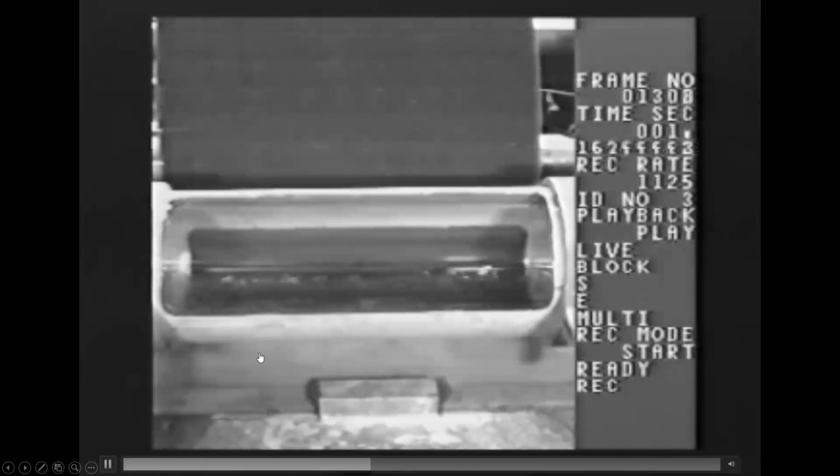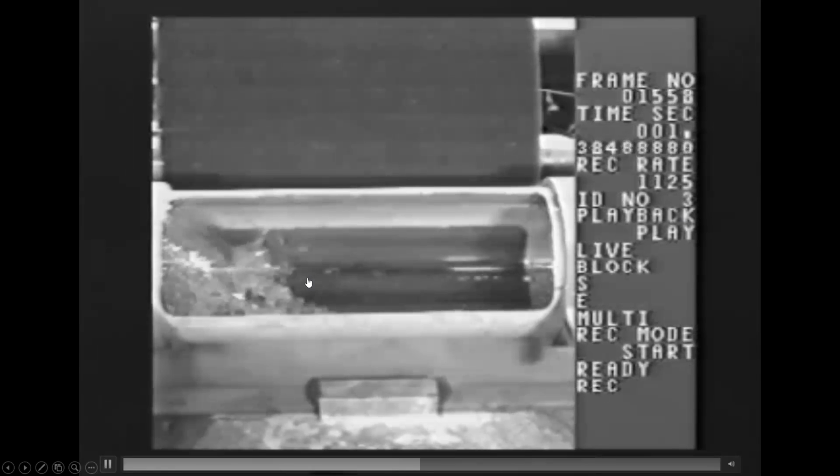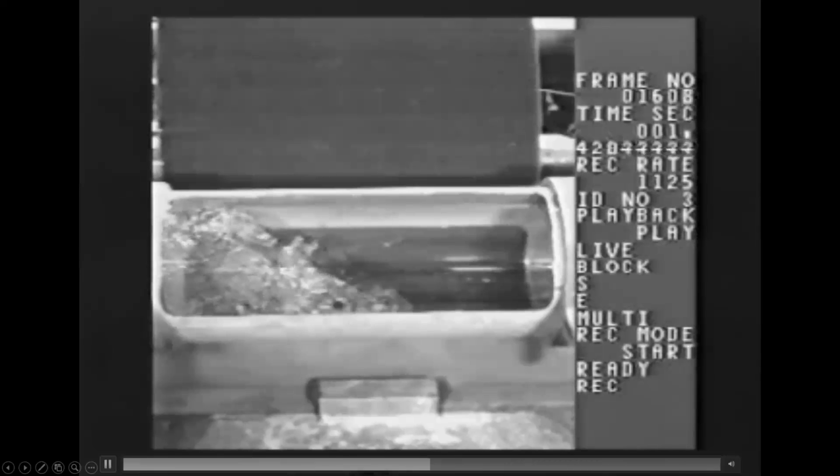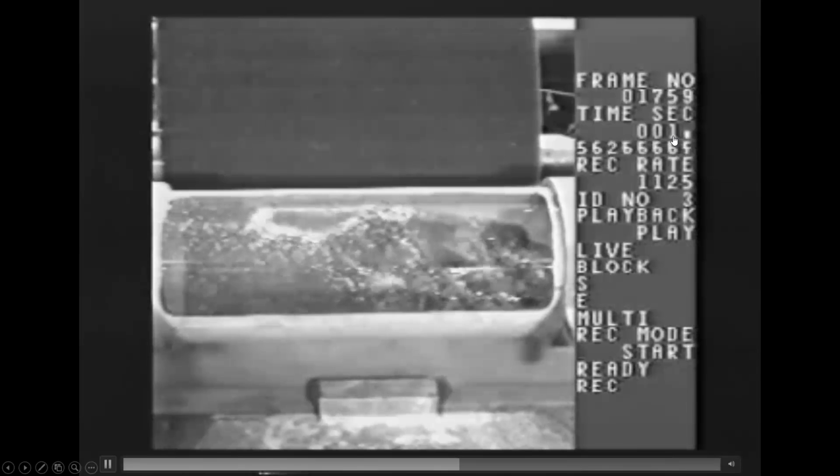What does it mean, the water column returns? It means that the pressure goes above the vapor pressure and the vapor transforms back into liquid. And that's when you have that high spike of pressure, okay, the upsurge. As you can see, not even 2 seconds.